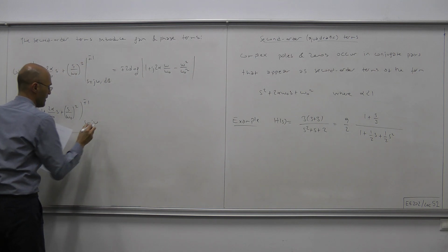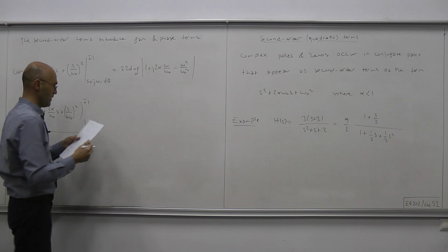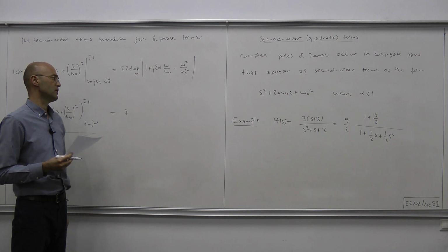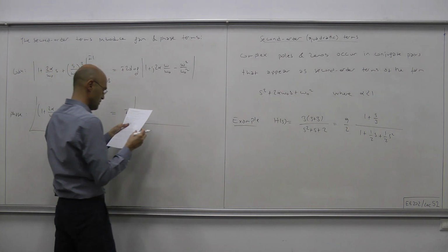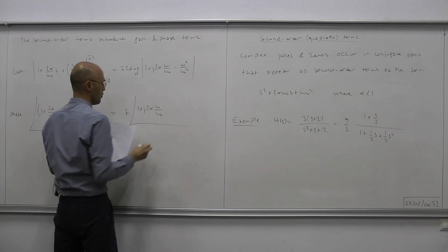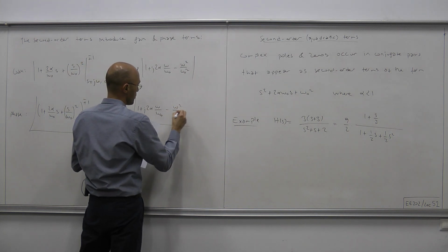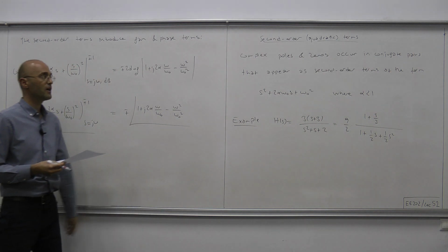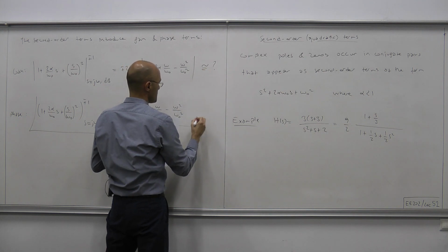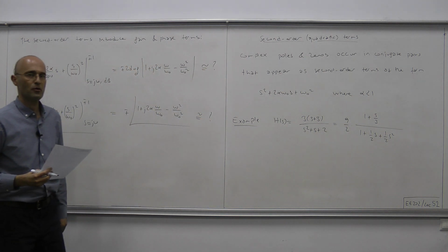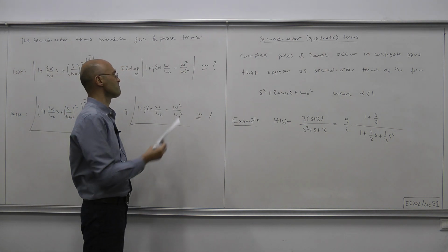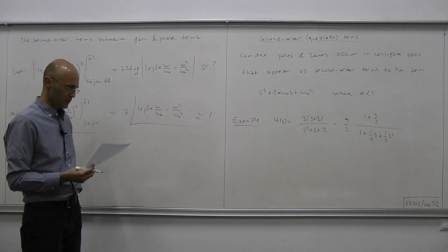And we evaluate that at s equals j omega. That means we're dealing with plus for the numerator and minus if it appears in the denominator, the phase of 1 plus j 2 alpha omega over omega 0 minus omega squared over omega 0 squared. Now the question is how to approximate these terms. Again we want to make use of some asymptotic approximation when we sketch the Bode plots for the corresponding terms.